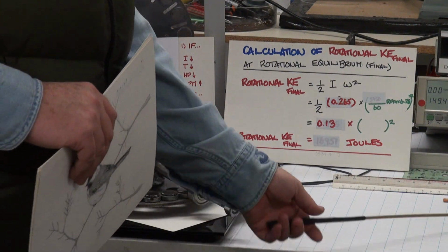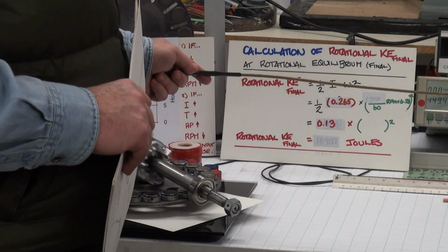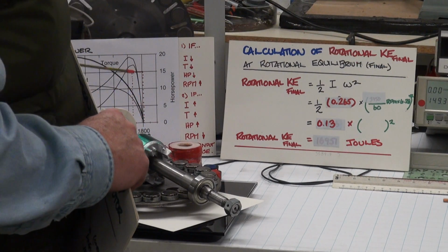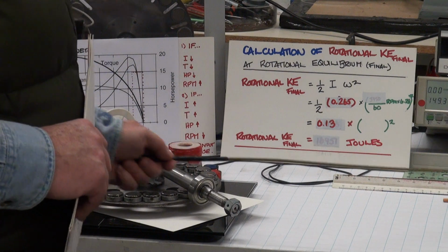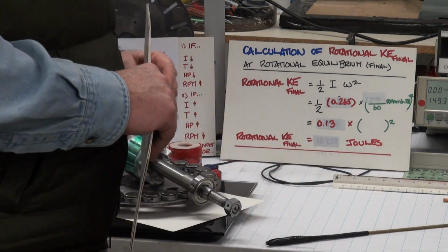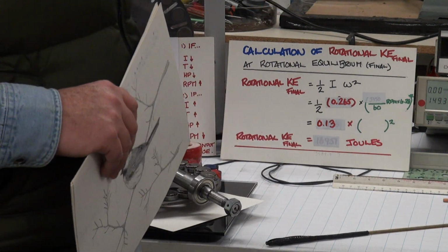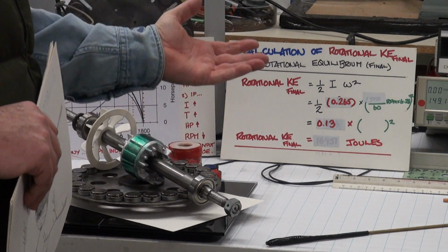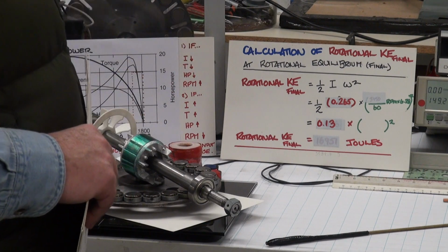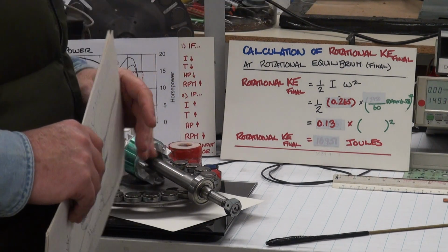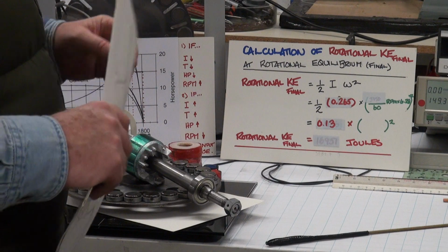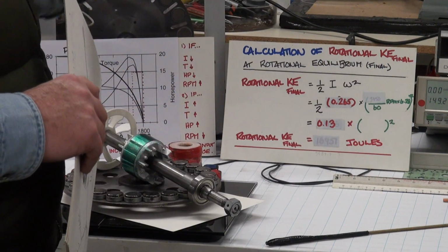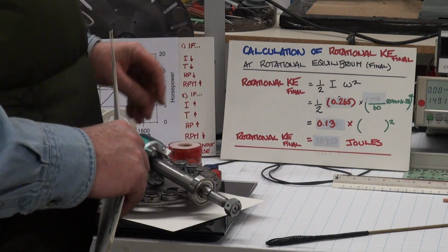And what you'll notice is the power to the prime mover will drop considerably as the speed increases. And what's happening in our system is the torque that's supplied by the prime mover is dropping while the ReGen-X motor is accelerating the system, and a new rotational equilibrium will be established at a higher speed.